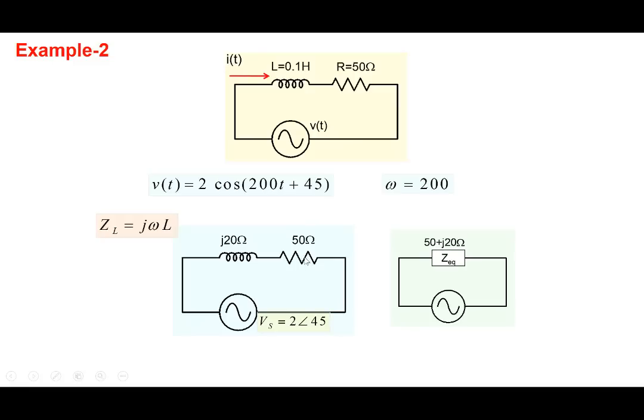as a resistor, 50. Now after that, note that the circuit is like the regular circuits that we handled before, consisting of resistors and dependent sources. The only thing is some of the elements have complex values here. So these two are in series, we can combine them together. The concepts of series and parallel are all valid here also. So we can combine them and write one equivalent impedance, 50 plus J20 ohms.